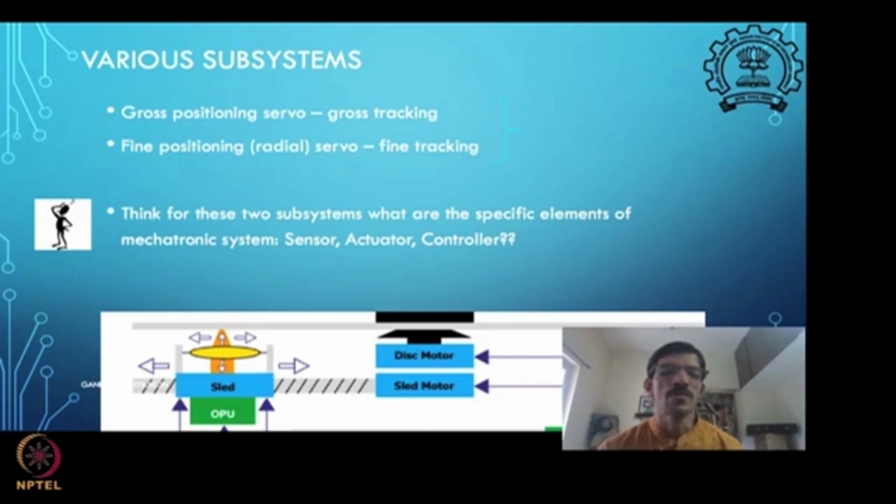You may say this is very fine positioning which is required, so I may use piezo actuators, which will give you fine positioning. Fine, that can be one possibility. How would you set up such a drive? Piezos typically need very high voltage to operate. Do we have such a high voltage operation possibility? Does any other kind of actuator come to your mind which can do this job?